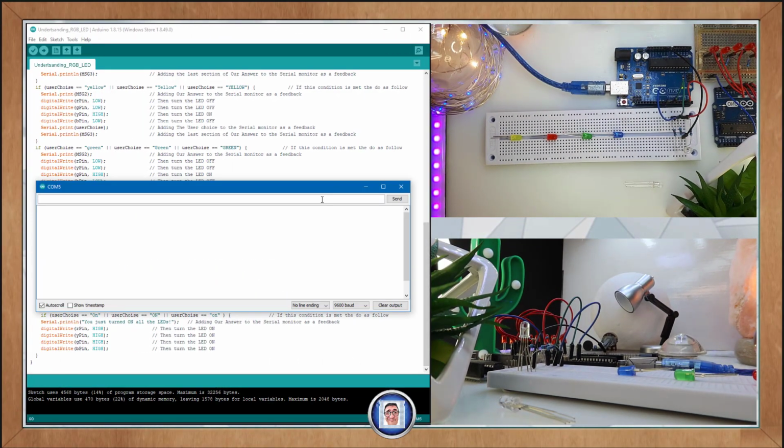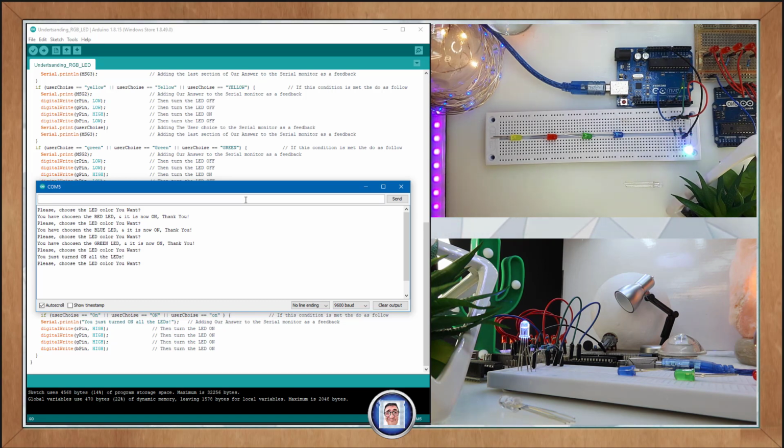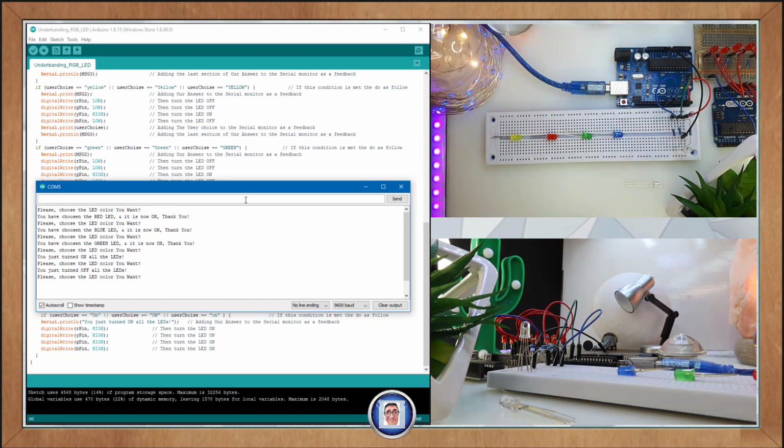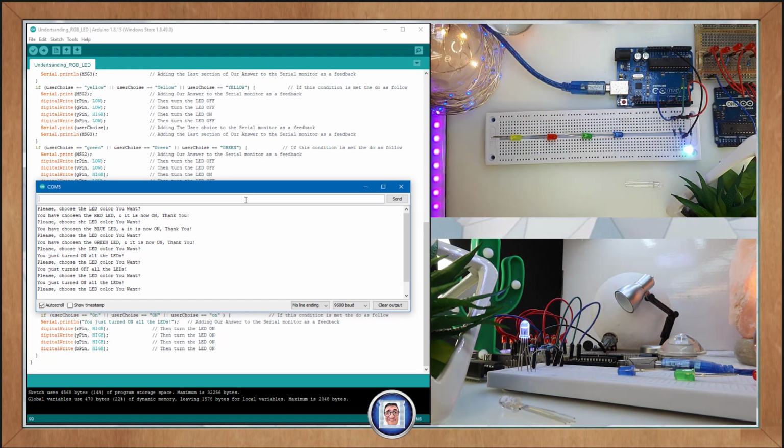Now we can bring in the IDE without changing the sketch. And in the serial monitor, starting with the red, it works, the blue is okay, then the green, no surprises here. But if I turn all of them on at the same time, then we get a white color, and this is normal. Now I turn them all off, but you can see that it flickers. We just have to adjust the wires by fiddling a little bit with them. Once you've done that, as you can see, it's okay.